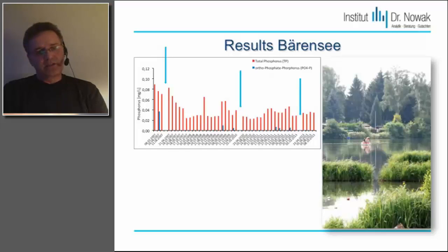But because of the external source like swimmers, we had to add after 3 years again a smaller dose of 3 tons, and after again 3 years an additional dose of 4 tons to keep the phosphorus concentration below 40 micrograms.